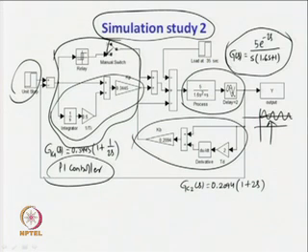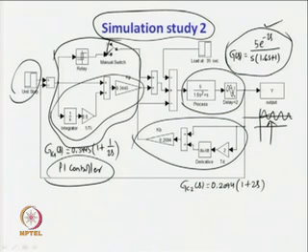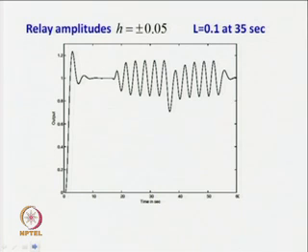As you know, when the relay is connected in parallel with the PI controller, the offset in the output can be nullified, and thus it is possible to get symmetrical sustained oscillatory output with no effects of static load disturbance. Now, for this integrating process, the static load is injected at time t equal to 35 seconds, and let us see the type of waveform we will expect during the auto tuning test.